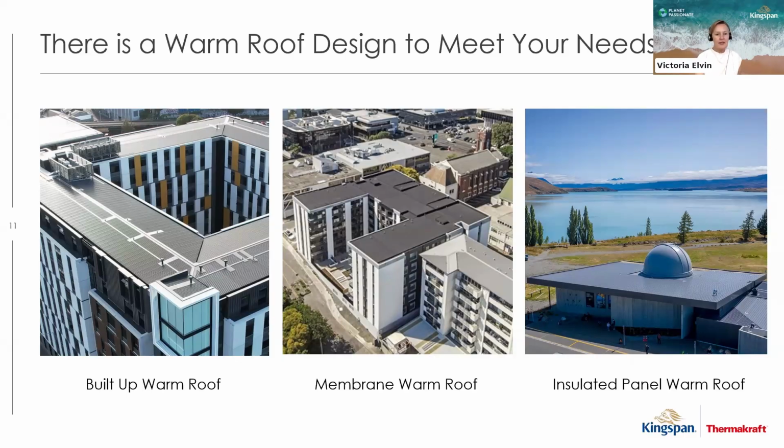The external cladding in a built-up warm roof can either be profiled metal, which has a minimum pitch of 3 degrees, or it could be a membrane, which can go down at times to 1 degree. We know E2/AS1 will say that a membrane is a minimum pitch of 2 degrees, but many membrane suppliers have a certification that will take their membrane down to 1 degree. It just needs to drain for roof drainage on that front.